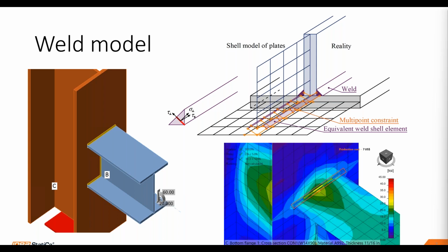So that element considers the weld throat thickness, position, and orientation. And the elastoplastic behavior is considered in the material nonlinear analysis that the software does with this model. So the stress peaks are redistributed along the weld length. This is an effect of using elastoplastic material. The elastoplastic model of welds gives real values of stresses, and there is no need to average or interpolate the stress.